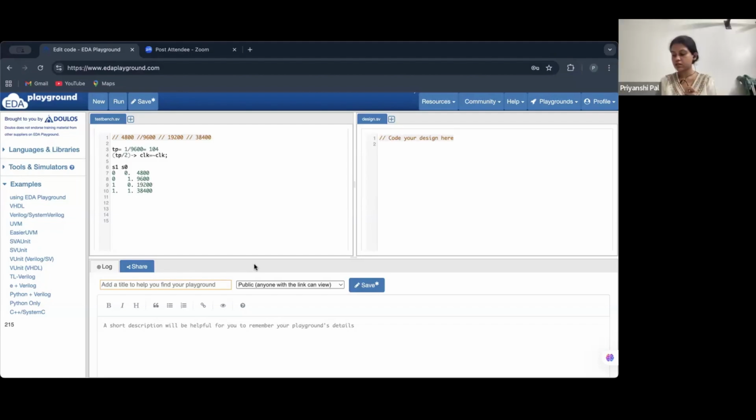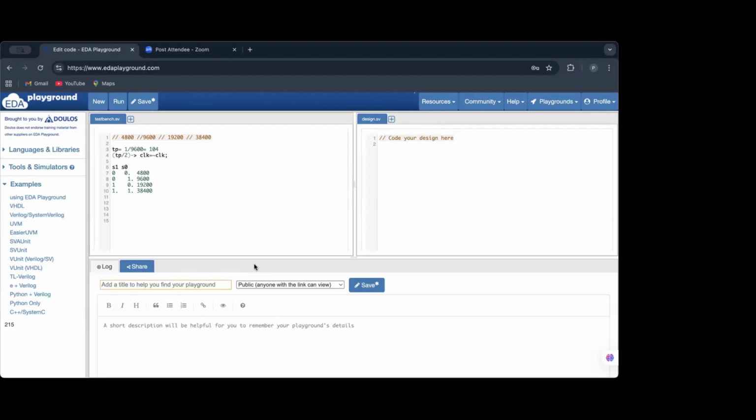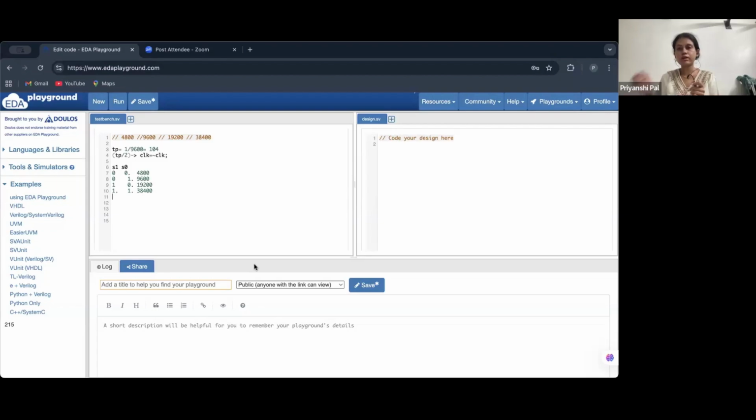Like, ma'am, in I2C, the master and slaves are connected with two transmission lines, which are SDA and SCL. SDA is basically bidirectional, and also it is local to the slave and the master. Also, ma'am, as I mentioned earlier, SDA is the only line wherein the data will be transmitted.